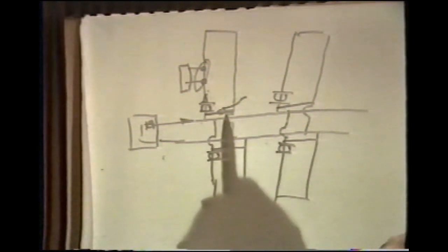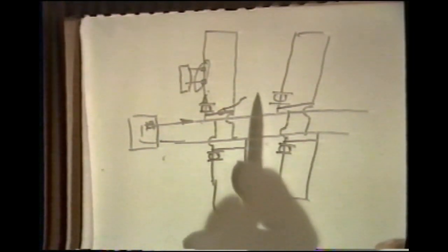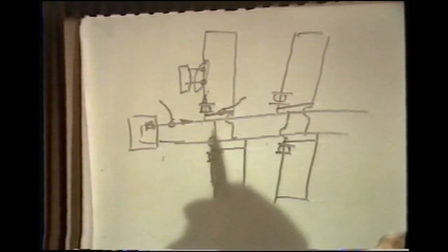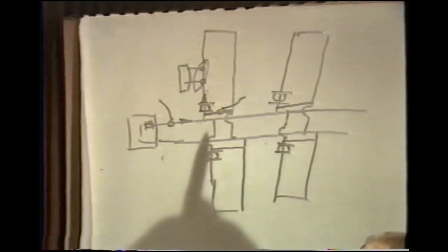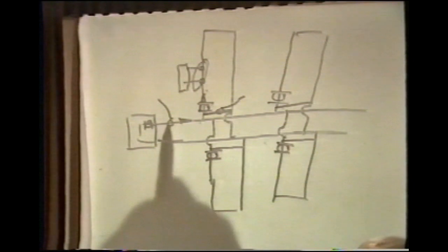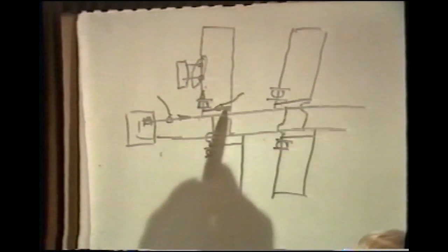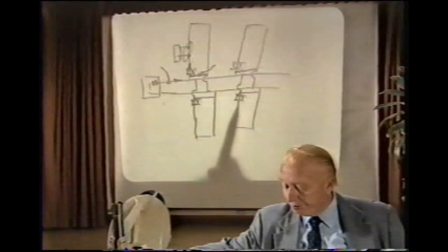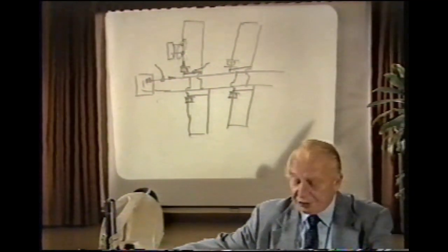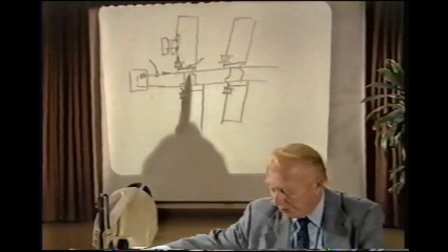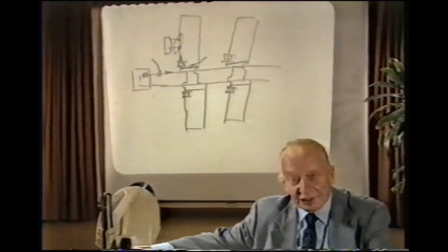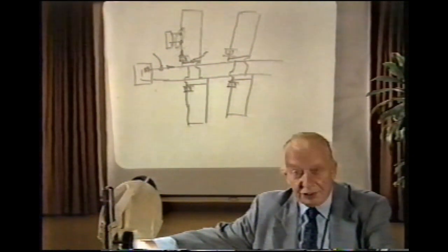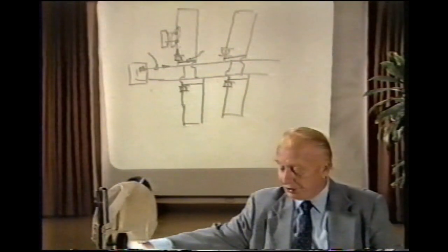And because of the disassociation of the secondary circuits from the primary circuits, we were able to provide a workable solution. We had, of course, to increase supply water temperature through the primary distribution system slightly. And because of this and the mix that occurred then at the inlet to the secondary building circuits, we were able to provide a completely workable system. Now, this then proceeded in terms of application from this very simple example, derived from desperation, if you will, into massive usage of primary, secondary pumping techniques.